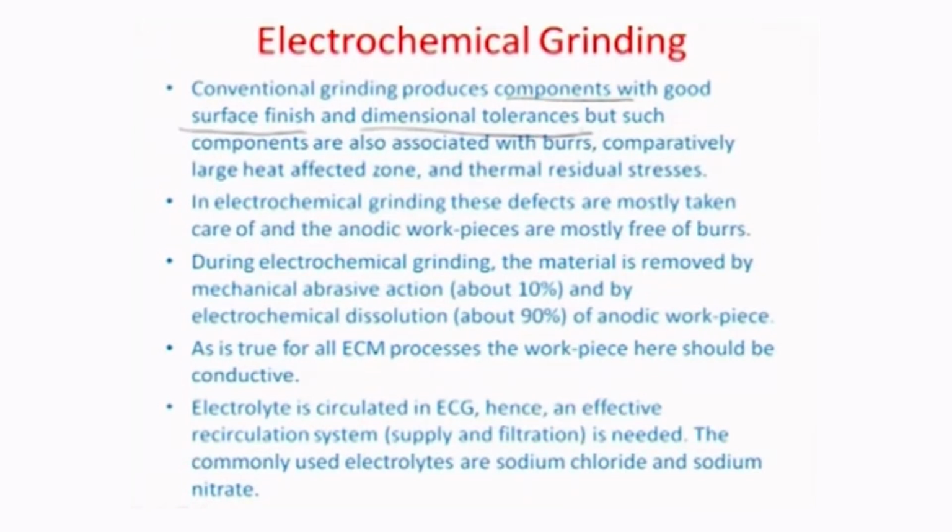But the dimensional tolerance gets significantly affected with associated problems like burrs, or comparatively large heat affected zone, or thermal residual stresses, which would create a sort of breakdown of the surface structure, because grinding is a multiple cutting tool with a lot of abrasive particles which are embedded onto a matrix which rotates with respect to a workpiece, and there is a heavy amount of plastic deformation on the surface, which happens because of the small abrasive grains continually hitting the surface at a very small depth of cut.